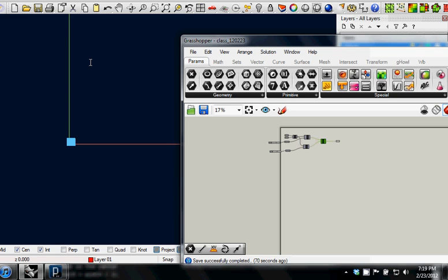And when we're talking about a relative coordinate system as opposed to a global coordinate system, instead of X and Y, we say U and V. And instead of Z, we say W. So if I were to take this pin off the surface of the table, and hold it 1 foot in the air, it may be like 4 feet off the ground, but it's 1 foot off the table. It's like 4 feet in Z, 1 foot in W, relative to this table.